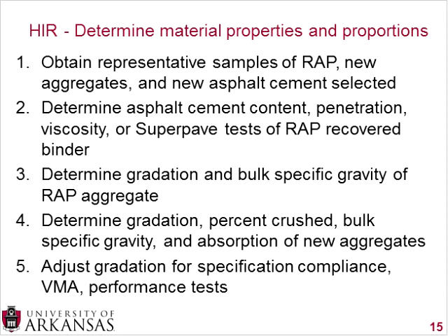You need to determine the gradation and the bulk specific gravity of the RAP aggregate. This is a little bit difficult because after heating the in-place material, you can either scarify the material or you will mill the material. This is a problem very similar to cold in-place recycling: you need to simulate as best you can how the material will act in the field, but simulate that in the lab.